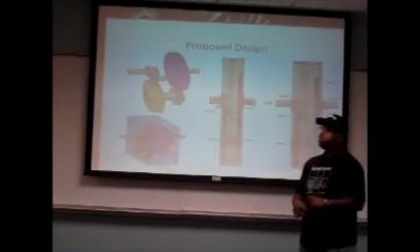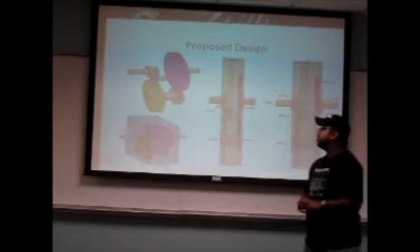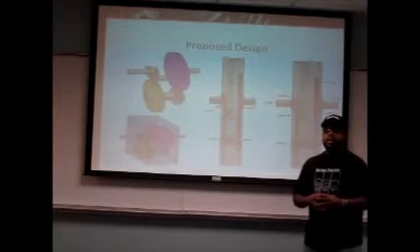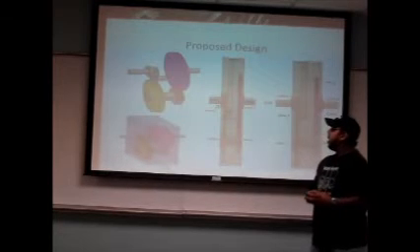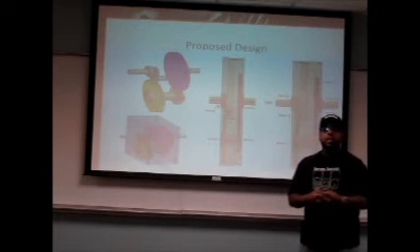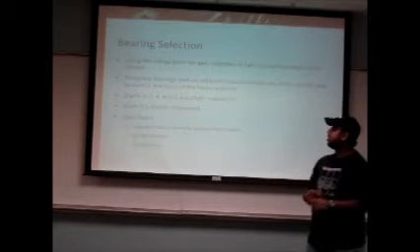On shaft 2 is also bonded gear 4, which drives gear 5. As you see, gear 5 has the highest pitch diameter and drives the output shaft. An important thing to note is that we were able to meet our specification of having the input and output shafts on the same axis.